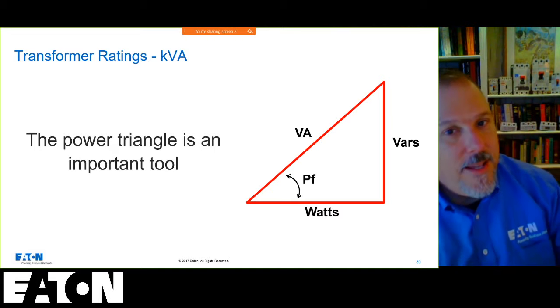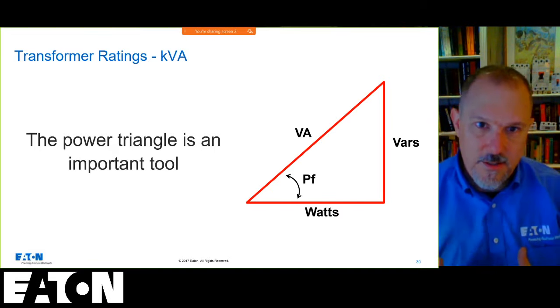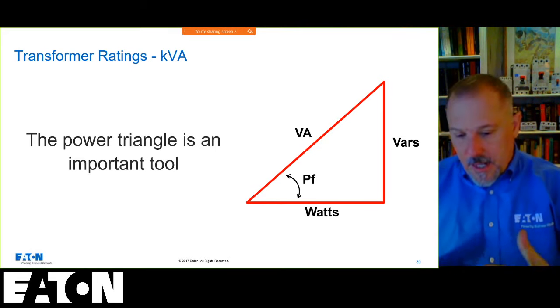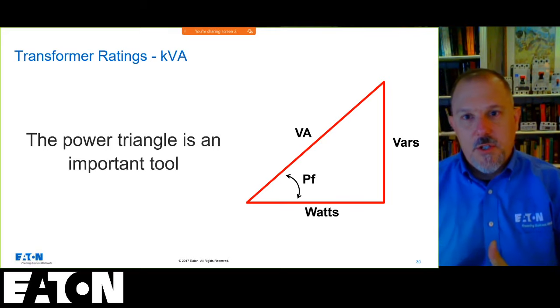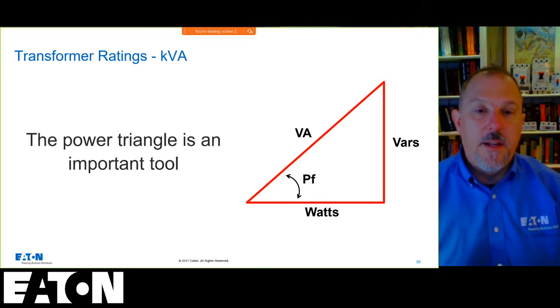Now, we size transformers based on VA, not on watts. Okay, so I see this in lighting calculations. I've seen people do this where they talk about watts per square foot, and we have to remember that we use this power triangle.